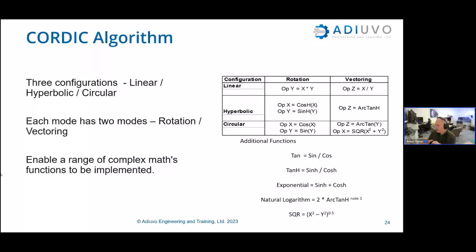When to use CORDIC or when to use lookup tables, I'll come back to at the end, because I'm now a little nervous that we're not going to get through everything in the time. But essentially, it comes down to your experience and what you need to do. A CORDIC can actually be quite small and cover quite a range of things. But there's nothing wrong with lookup tables neither. One of the big decisions would be precision. Because obviously lookup tables just give you discrete outputs in between this value and this value. You've got lookup tables that drop out particular values, whereas with a CORDIC, it's a much smoother and a much finer granularity of it.